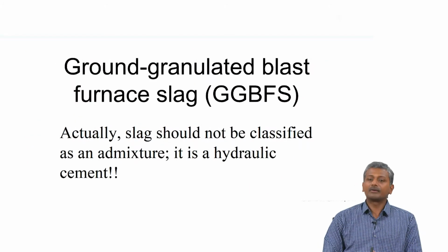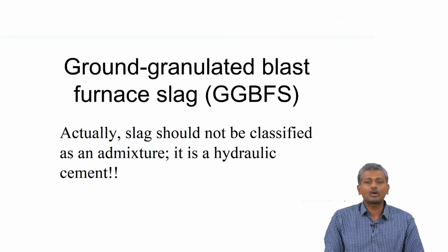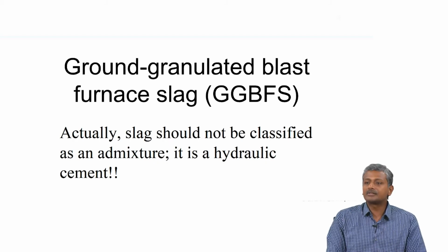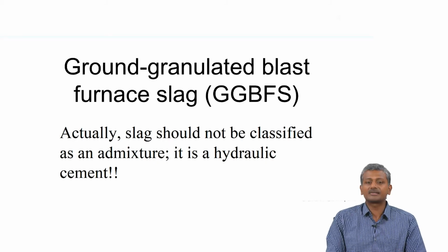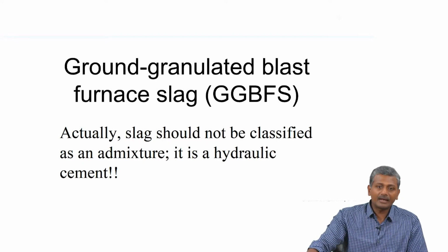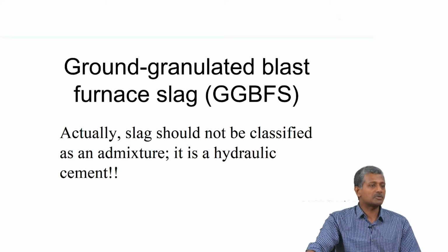Let us look now at granulated blast furnace slag. We discussed earlier that it is typically not included as one of the mineral admixtures or pozzolanic additives. It is called a hydraulic cement on its own, okay, because slag can react on its own, but then the reaction is extremely slow and needs some activation. This activation typically happens in the presence of Portland cement.